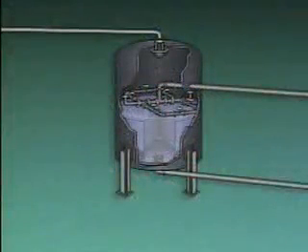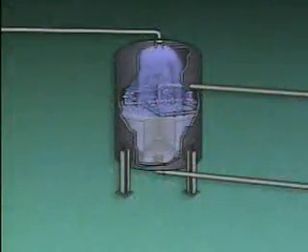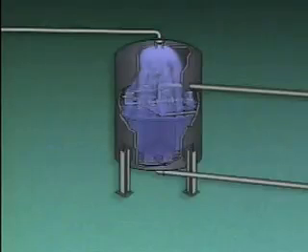Finally, in the rinsing step, rinse water enters through the water inlet. Rinsing removes the remainder of the salt solution and the hard ions from the softener. The rinse water drains out of the outlet and is pumped to a treatment facility.